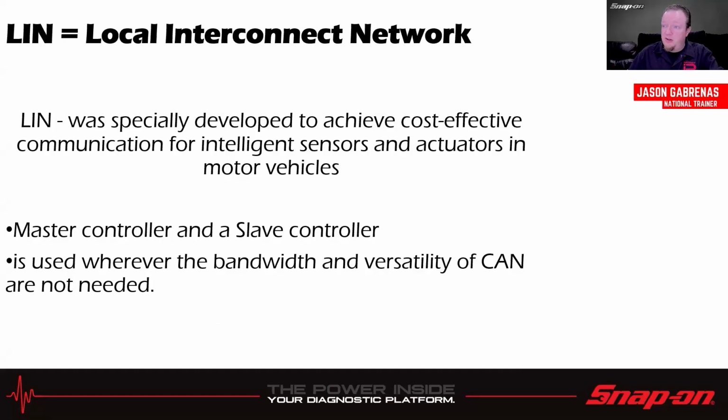It was specially developed to achieve cost-effective communication for intelligent sensors and actuators in motor vehicles. It's a master and slave type situation. So think of things like, to save complexity on the window motor circuit, I press down on the window switch. It's going to send a signal. That'd be the master. It's going to send the signal down to the window motor, and it's going to tell